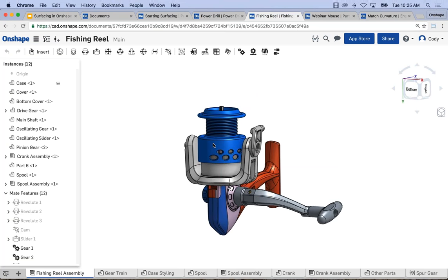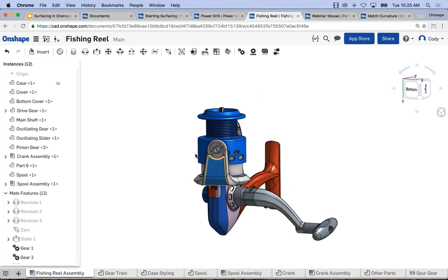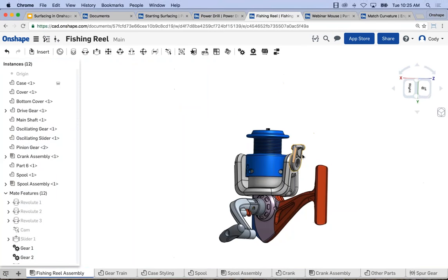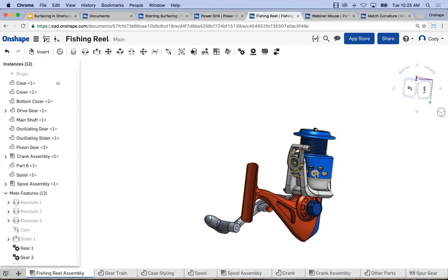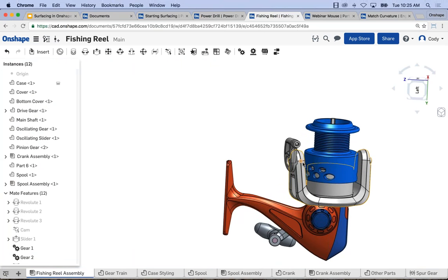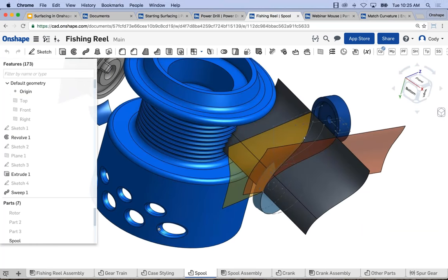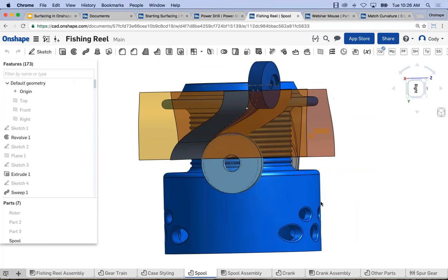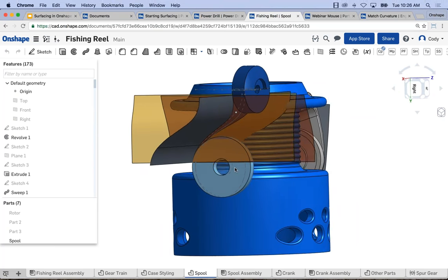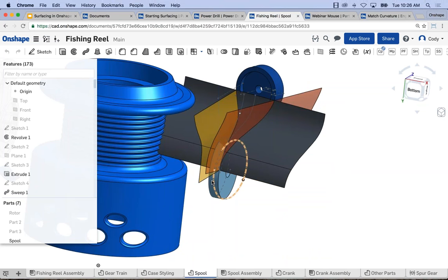So, this is a spool that rides up and down on a thread, and the actual end pieces and all these various things have varying angles, compound angles, right? So this is rotated 15 degrees from this axis and down in the y-axis by 10 degrees, so you have a combination of things. And that's another great example where I can construct surfaces just to reflect the relationship between parts. So here's that same spool, and it has a few important bosses. And I want to be able to construct maybe a loft between the two bosses, or maybe a sweep between the two bosses. And surfaces give me an important role there, right?